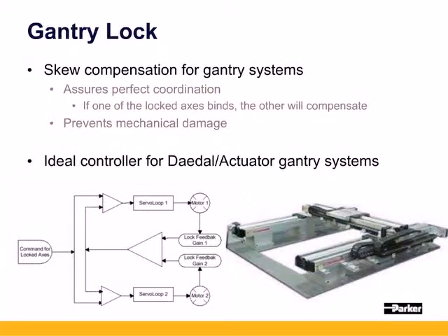The ACR9000 series controllers also has an advanced feature helpful in Gantry systems when two motorized axes are run in parallel. Many controllers require the X' axis to be set to follow the X axis. The X axis position is being commanded to move and has its servo period update, and the X' axis is set to follow this value, so it's always one servo period behind as it has its own update. Also, if you're trying to command very small incremental moves, then you could have one axis fighting the other, so tuning is an issue, where you detune the X', but that also decreases your force available.